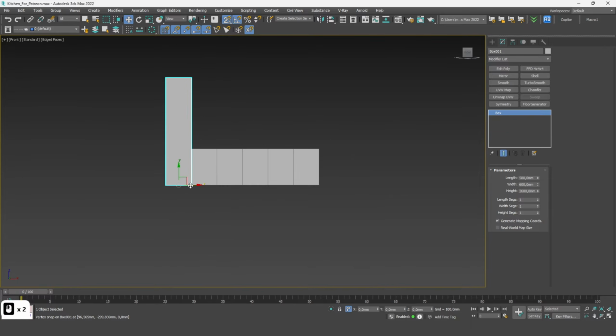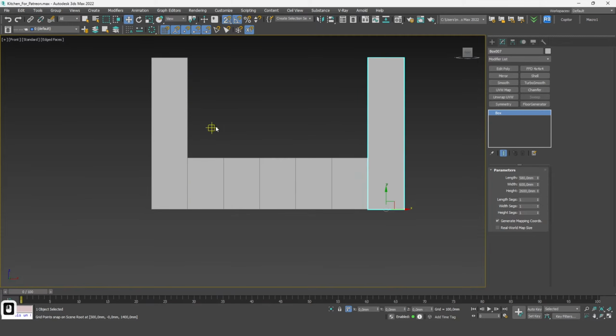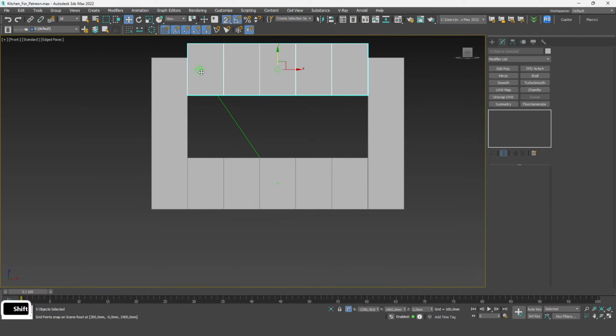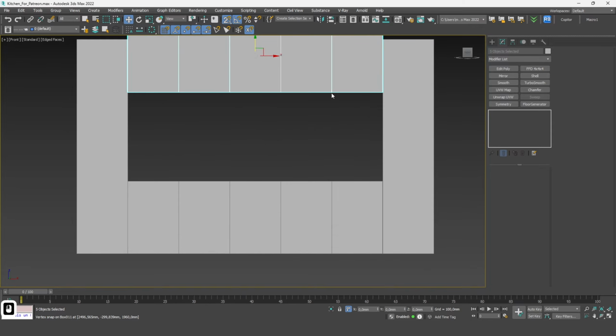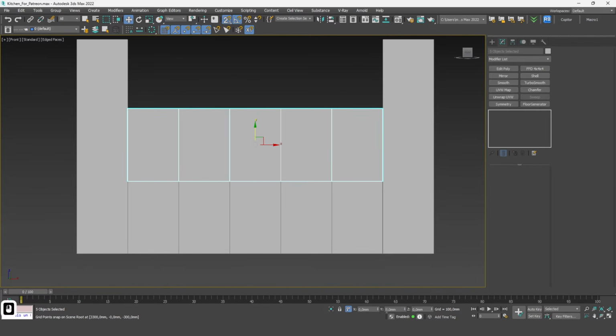Now select the case and copy it in the opposite direction. Now we select the middle blocks, from which we will make the upper cabinets, so we copy them and using the offset mode transform, set the coordinates to 670 mm along the y-axis from the lower cabinets.